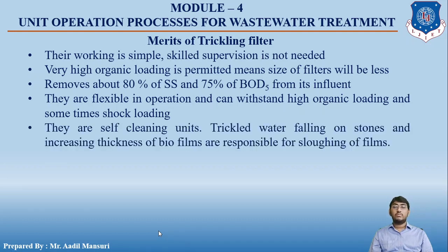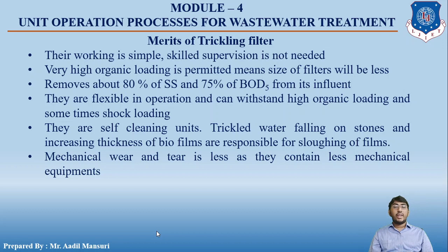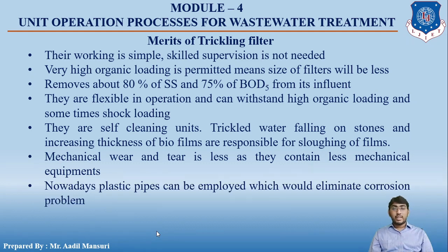They are self-cleansing units. Trickled water falling on stone and increasing thickness of biofilms are responsible for sloughing of films. Then mechanical wear and tear is less as they contain less mechanical equipment. Nowadays, plastic pipes can be employed, which would eliminate corrosion problems. So these are some of the merits of trickling filter.